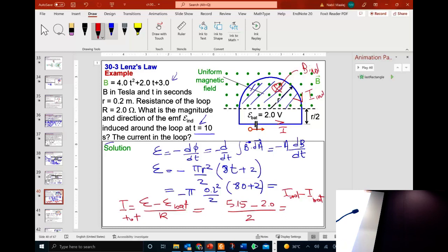It's inducing a current, and in this case, it's inducing a current and an EMF opposed to the existing battery. This is very interesting. So if you have a circuit and it's close to a very strong magnetic field that is changing, it will interfere with your circuit. So you have to shield your circuit, otherwise you'll have problems.